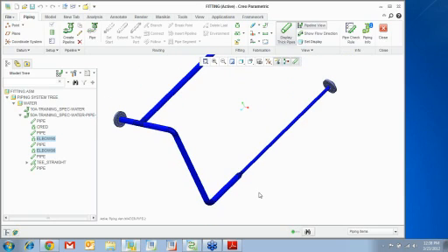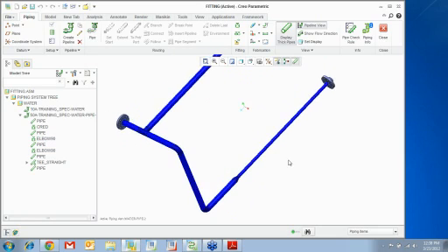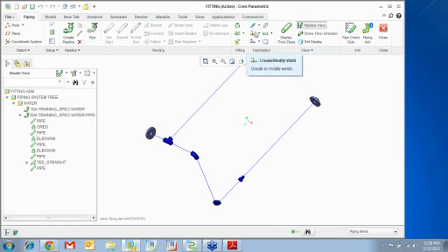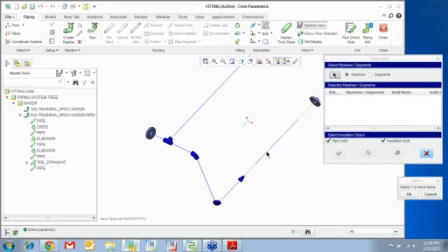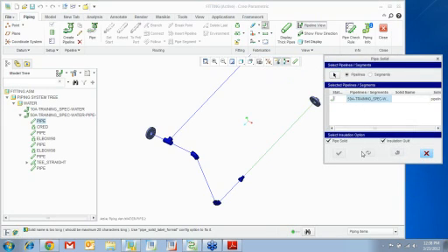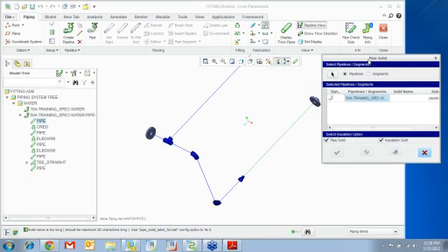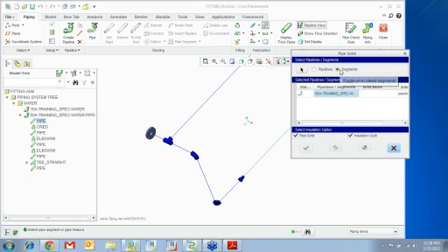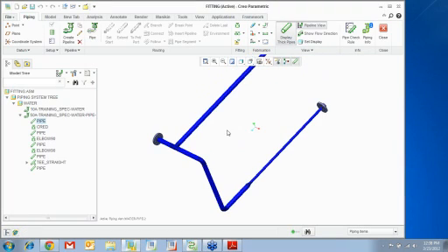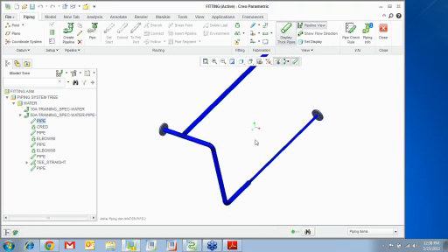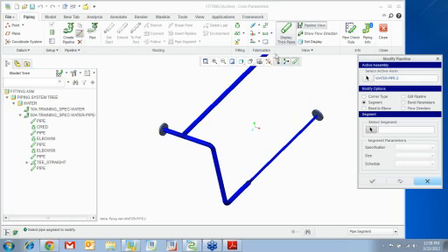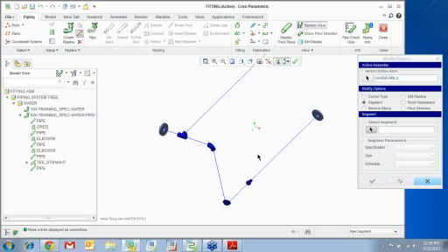Right? So people who don't want to use schematic, but they want to kind of route their pipes with a certain spec, can always use this. Okay, since welding, creating spools, creating a solid pipe. So I pick that and say okay. Right. So it's going to go ahead and create a pipeline wherever you need. Right. So there you have it. Okay. So this would be a kind of spec-driven pipeline. So if you can edit the pipeline, you can see right here when I try to edit.